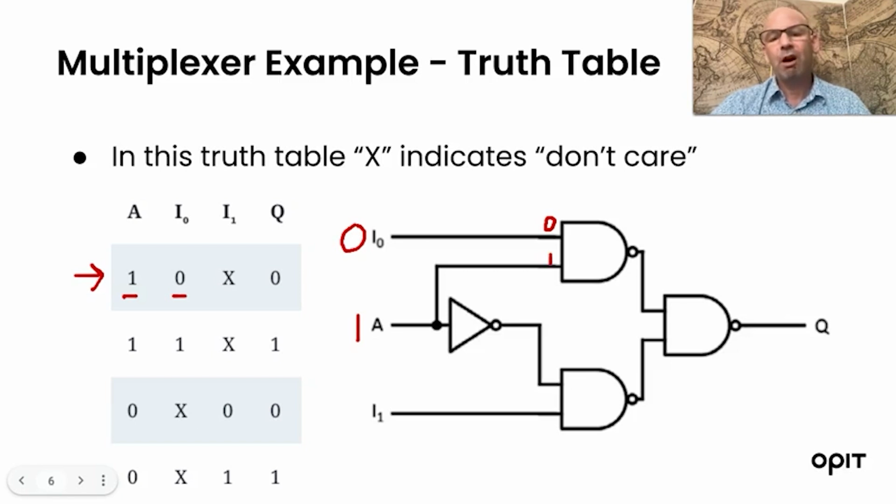Now with our AND gate, a 0 and a 1 would end up being 0. It's not A and B, so in that case the result will be 0. But with our inverter here, it's the opposite, so this value becomes 1. Now with our A as a value of 1, we pass it through our NOT gate, so it passes in as 1, but because it's an inverter, it passes out as 0.